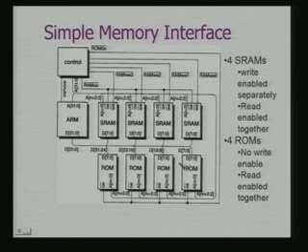Now, here what you will find is that if you see the address buses, the way it has gone in, this is a 32-bit address, okay, and this 32-bit address is fed to the controller as well as to these RAMs, because this address has to be decoded by these RAMs to select the individual rows. The decoding logic is part of this SRAM module, okay, and this is being fed here.